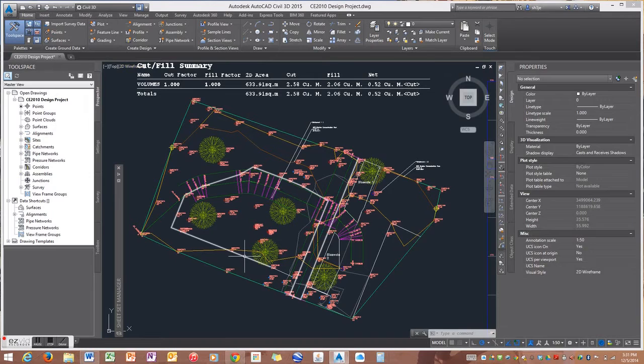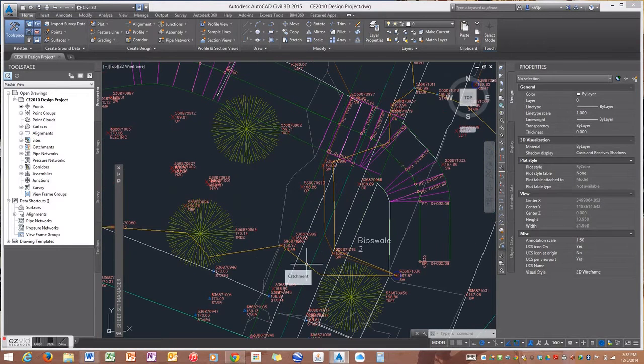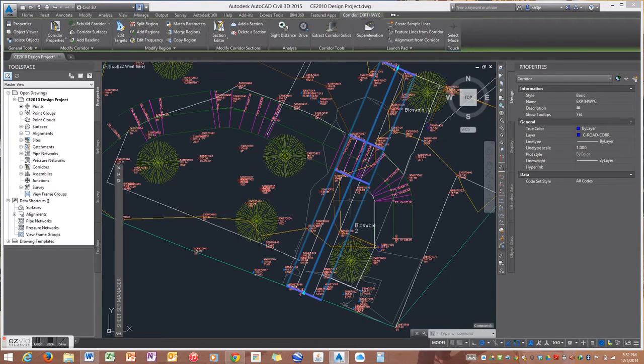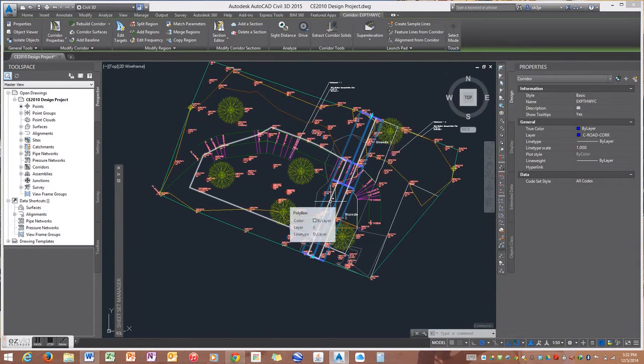As you can see from this polyline here, this outlines the existing pathway before my proposed design. And what I did was, after observation, determine that this was the main route of travel here, and focused my expansion on that. So as you can see from this corridor, increased from the existing, here highlighted in white, 15%, so we will have 3 meters across for the duration of this existing pathway.